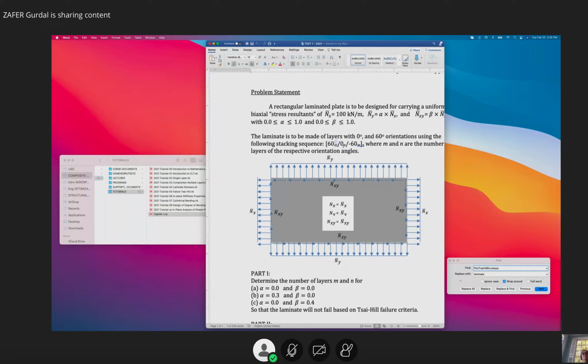So you'll have to introduce all kinds of situations where if M wants to be 6 or 7, you need to start distributing those plies through the thickness by interlacing them with other orientation angles. This is a major complication. And I'm not going to do the design of that for bending manually, the way that you're doing for the in-plane problem. It's too complicated.